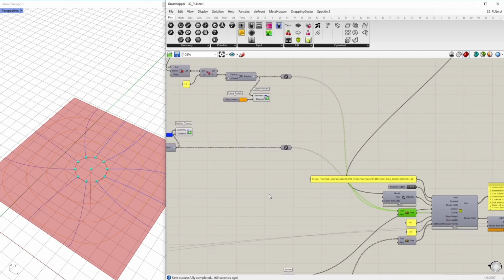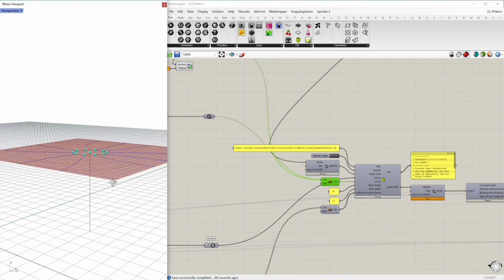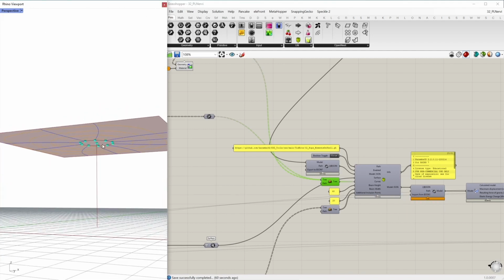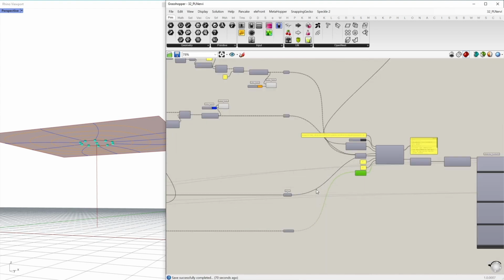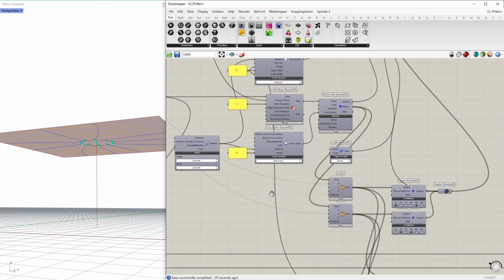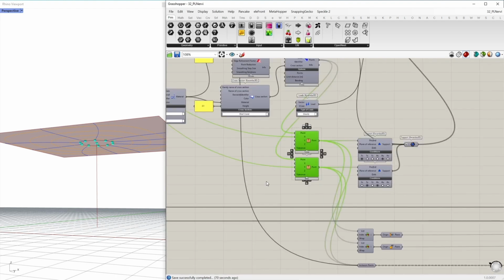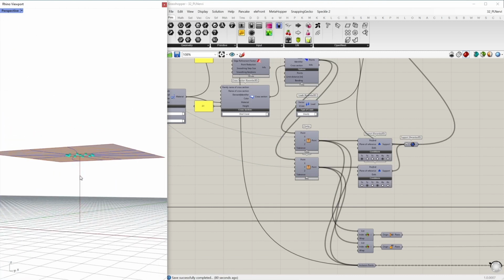Then we input the curves, the orange and the blue ones, the beam height and the beam width, which are the cross-section values for the downstanding beams, and additional inclusion points, which are in this case the new support points holding the slab on this side and on this side.